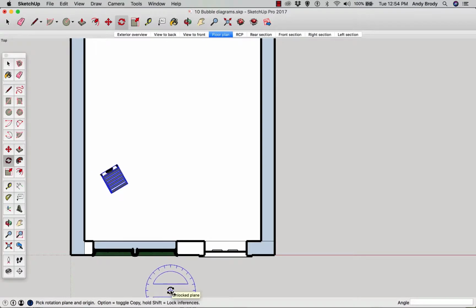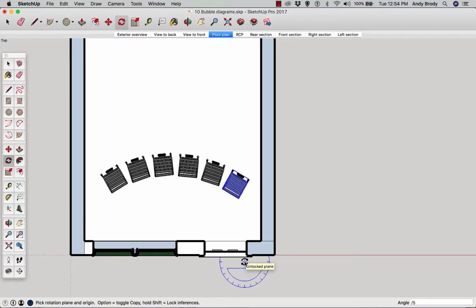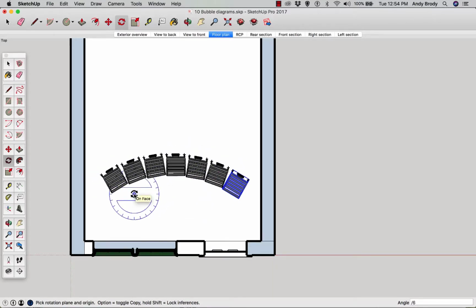and copy. This time, I'm going to plant the center of my rotation here off in the edge of the plan. I think it'll just look a little nicer. Now, I can drag, make the copy off at some angle on the opposite side of the room, and I'll use that slash modifier to create a series of copies right in between. And you see how SketchUp interpolates the angle from the first to the last. That might be too many. There we go. And there we go.